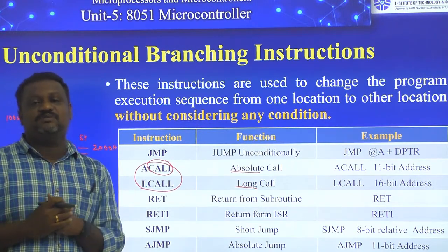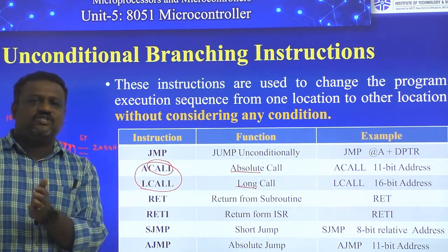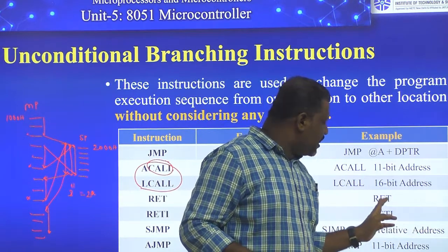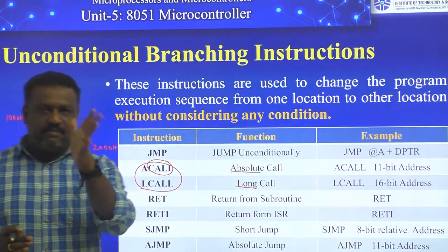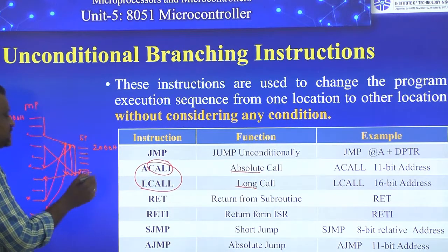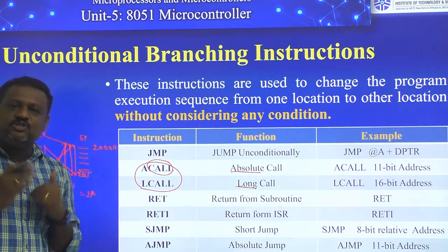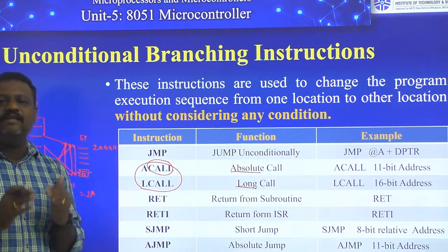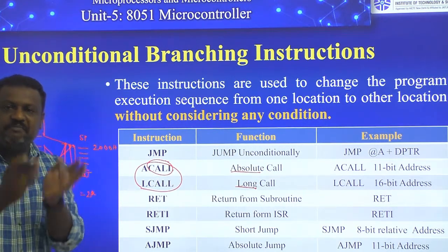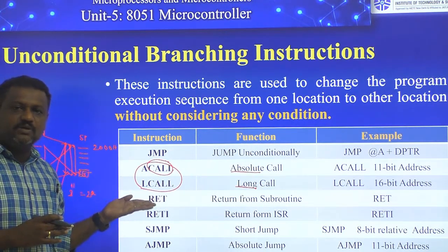RET means return from subprogram. The speciality of this instruction is that it comes under implied addressing mode. That means we are not writing any operand beside our RET instruction. You remember, friends, this RET instruction is basically used as the last instruction for any subprogram, or I can say in another way, as the terminating instruction for any subprogram. By execution of this RET instruction, our execution sequence changes from the subprogram to the previously stopped program. So that is an important thing regarding RET.